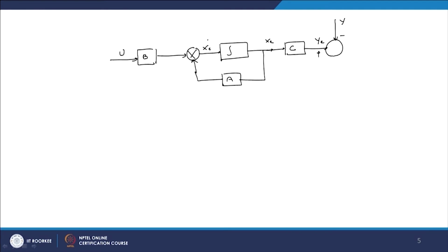Therefore, we are adding another controller matrix that is called KE, and here negative. So here, between the actual output and ye there is an error, and this error has to be driven through KE. What we want is that this error should be minimized, and this minimization is possible because of this KE and this particular state XC.